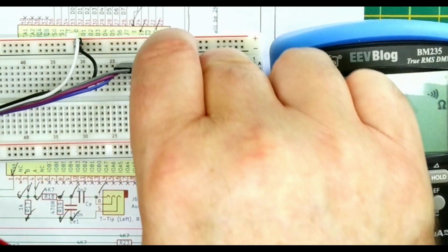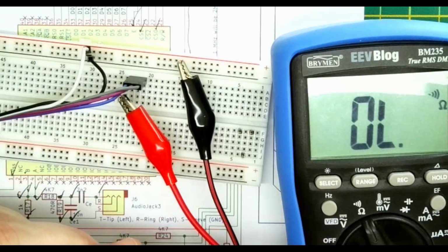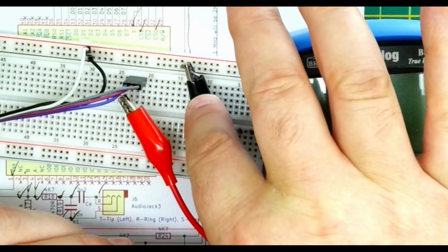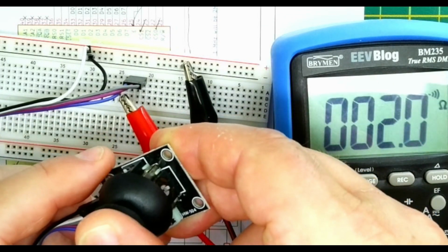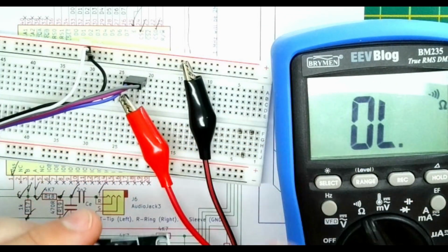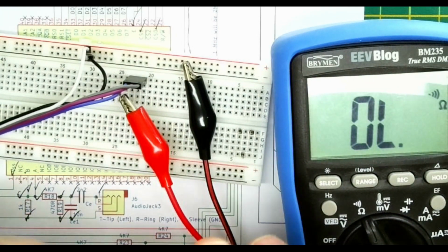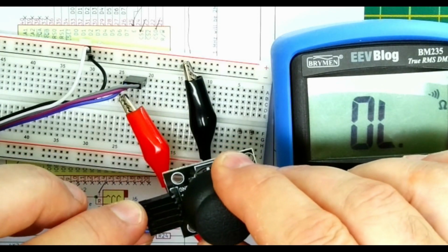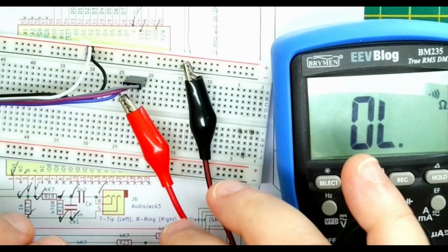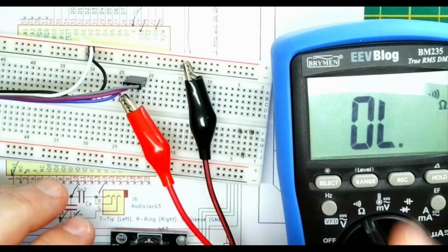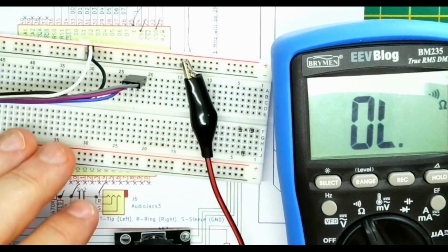So for example, if we plug one side to ground and the other side to the switch, and we press the switch, basically the switch grounds. When it's pushed, it will tie the input to ground, and because the input only has ground, plus 5, the X and Y outputs, and the switch, we can't control that. So we need to make sure there's a pull-up resistor for the switch, and then when it's pressed, it will take that low.